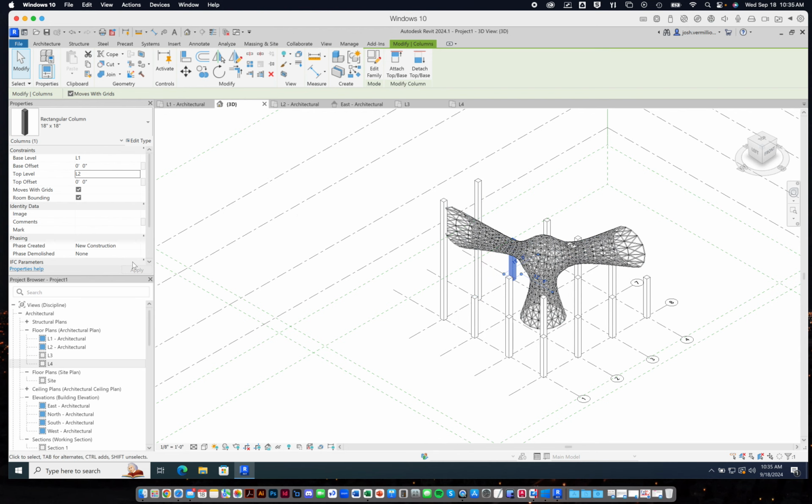I know it's probably dreadfully slow, but what I'd like for you to do over the weekend is to simply do this. Bring in your Rhino diagrid into here, establish the grid, then start to place objects along the grid. Columns, and then we'll do beams here in a minute as well. It seems a little repetitive, but what you will learn is the muscle memory of working inside Revit, which is different than AutoCAD and Rhino and Blender and all the Maya and all those other tools.